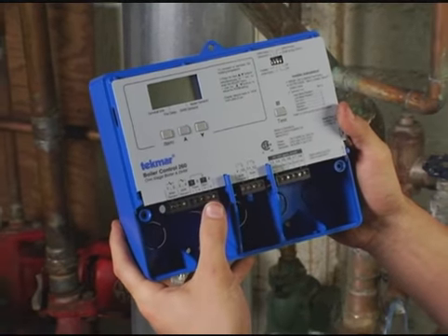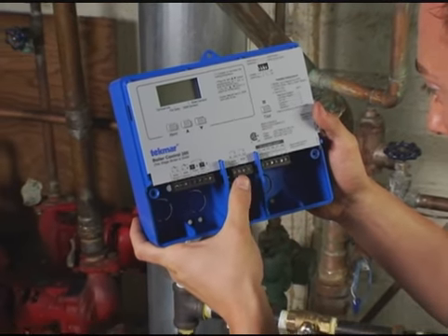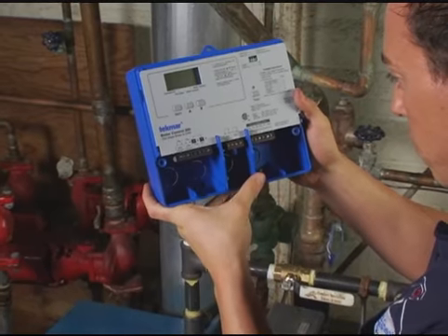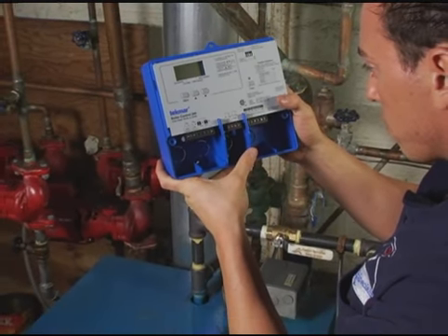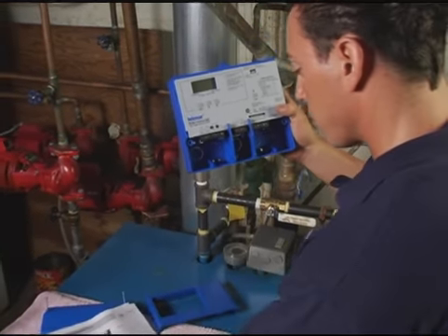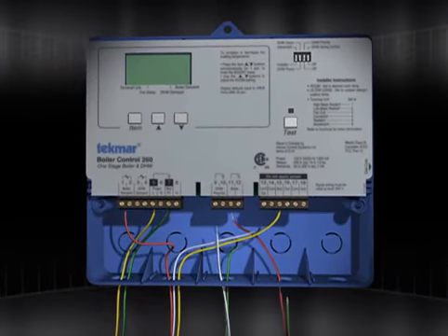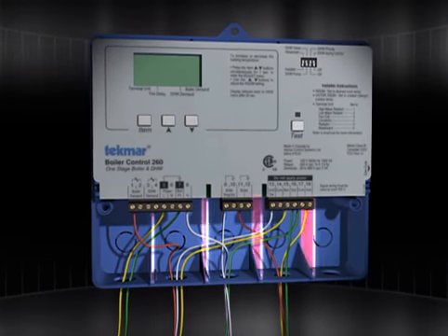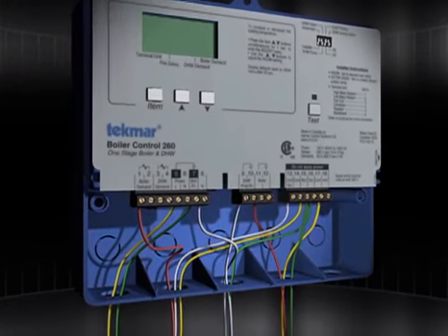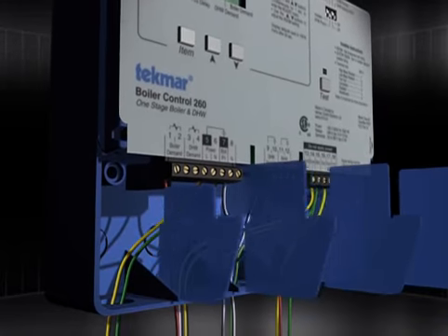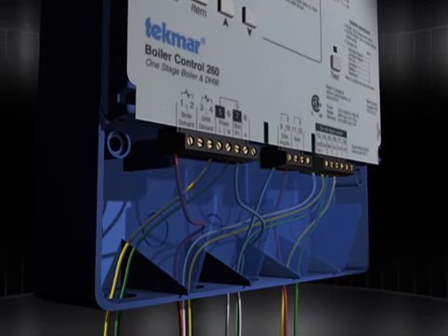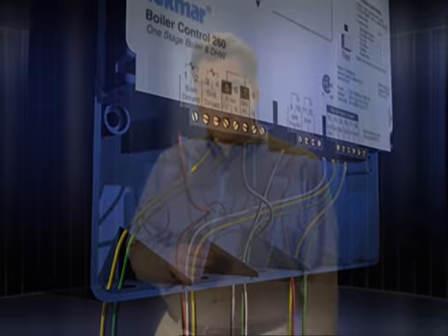Step 5. Mount the control base. On this model, all wiring terminates in the control base wiring chamber. But before removing the knockouts, check the wiring diagram carefully and arrange for wiring with common voltages to be in the same sections. During the wiring process, do not allow the wiring to cross between sections, as this will interfere with safety devices which will be installed later to separate line and low voltage wires.